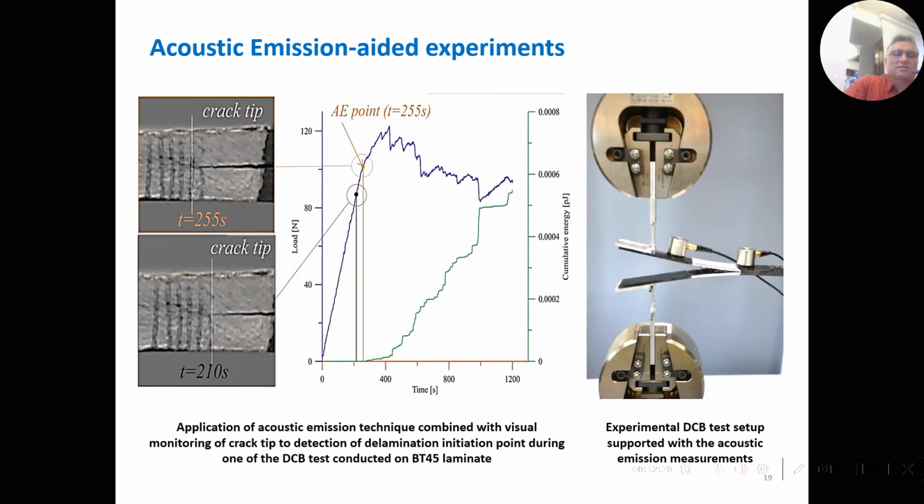So in the next slide, you have also other experiments, very recent. Just yesterday, my students sent me that data. At the moment they use two piezoelectric transducers also to measure additional parameters such as the velocity of the crack when it is active. And in this screen, you can see, first of all, the AE point, which is acoustic emission, and another point which is connected to the beginning of some nonlinearity. And you can also compare this with the photos of the real crack tip.